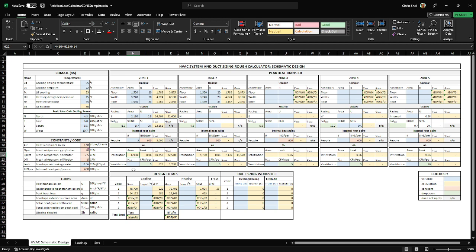Infiltration, the area here is simply adding up the walls, roof, and windows. I didn't do floors because I'm saying there's no infiltration through the floor, which isn't really true, because this floor is probably on grade. I should say that also. I just decided to skip the whole thing about the perimeter insulation. I just said we're going to call this a raised floor even if it's on slab. You can ask me about that in class. If you remember from last semester, that perimeter insulation thing with that variable F, we're not worrying about that. This is a basic model.